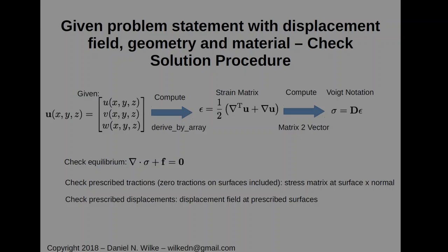Okay, if I'm telling you I'm taking a ruler and I'm pulling it by 1 centimeter, and the other side is fixed, which if it's a rubber ruler, I would be able to do that. But the bottom line is where I'm holding that ruler, there's traction. Yeah, I'm giving the prescribed displacement at that one end by pulling it 1 centimeter, but there's a traction forming then. I can go and look at that reaction traction.